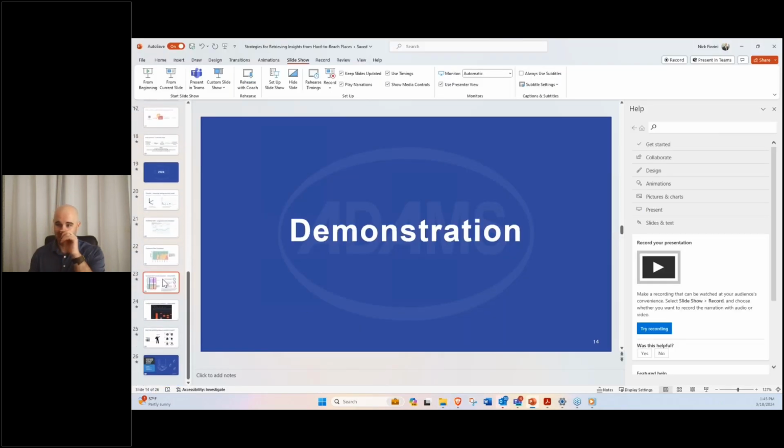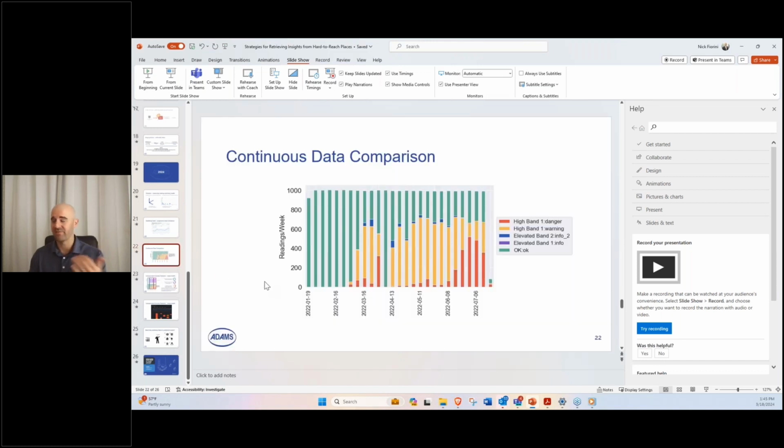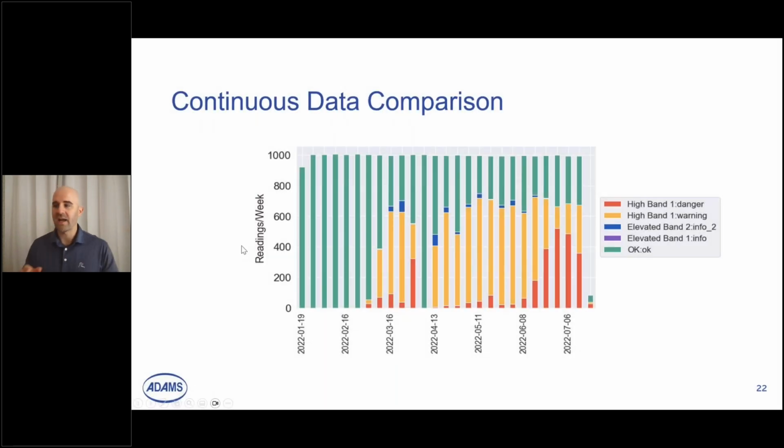But I'm going to skip ahead to this version of the vibration report to help you understand what this looks like. So over time, if this is a vibration sensor and each of these slices is a month, we could say in month 1 and 2, all of our readings for vibration fell within the healthy threshold. This sensor has a 0% health score, which is perfect. In months 3 and 4, we're starting to see the frequency and the elevation of these bands increasing. So our health score is getting worse. So maybe it's a 30 or a 40 now.